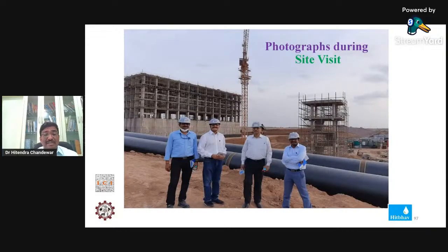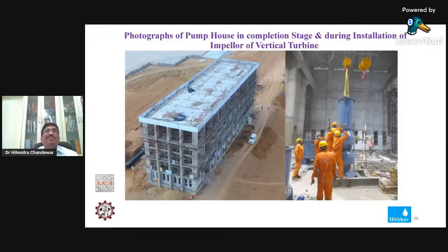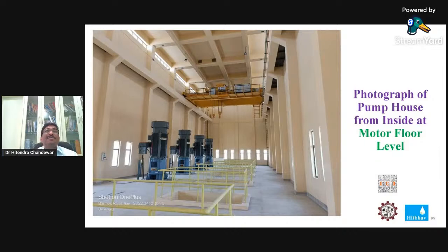Then now the pump house is at roof level. The work is at roof level. So erection of pumps is going on here. Then now this is the finished product. You'll find 4 pumps of 850 HP, and this 20 ton EOT, and this height is 16 meters. There is one more floor below this floor, that is the wall floor layer, of 4 meters. In total, it is about 18 meters above the ground, and below the ground it is 18 meters.